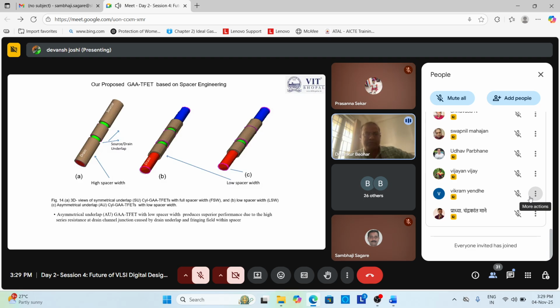And this green one, the cavity that you see here, is basically the underlap structure. These are the underlap structures over the tunnel FET devices. The same we can form over the MOSFET and FinFET also. So underlap devices means that portion we have reduced somehow. You can see that the gate length is reduced due to the cavity formation, in the first structure, from both sides, source and drain.